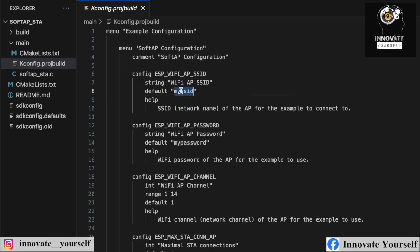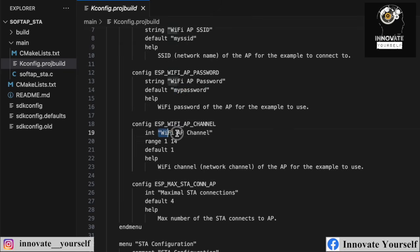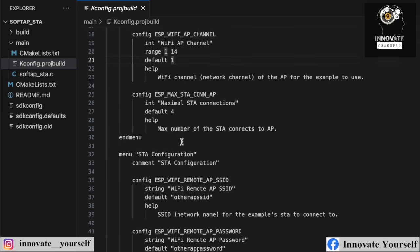By default, if you do not set up any SSID and password for your access point, it will be my SSID and my password. If you set up the password and SSID, that will be the one which you specify, but by default it will be this one, right? And you have the Wi-Fi AP channel, for which the default value is 1, and the range is between 1 to 14, so it can be anything. You can set it like that.